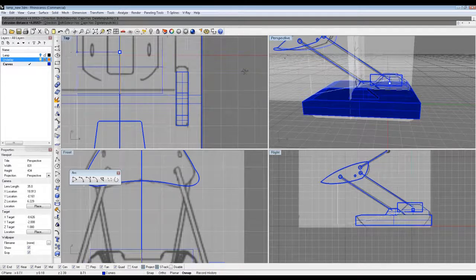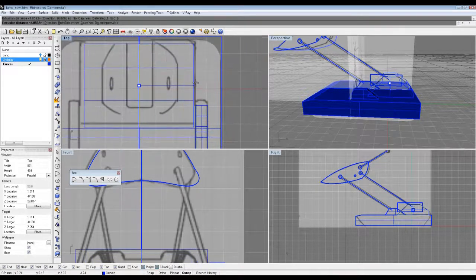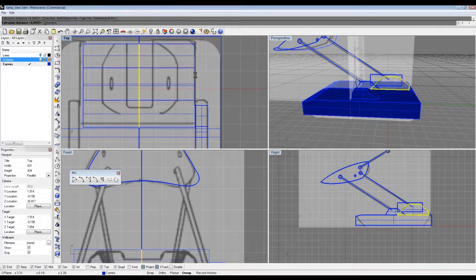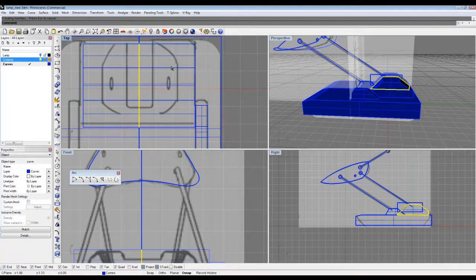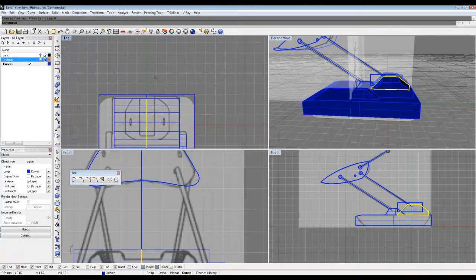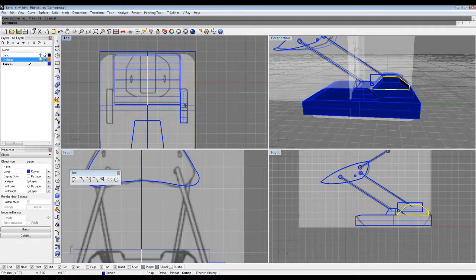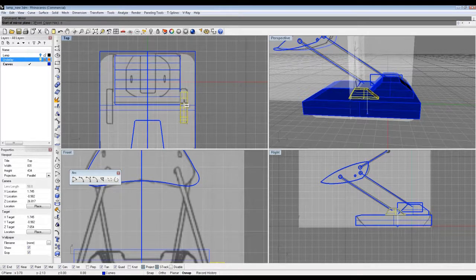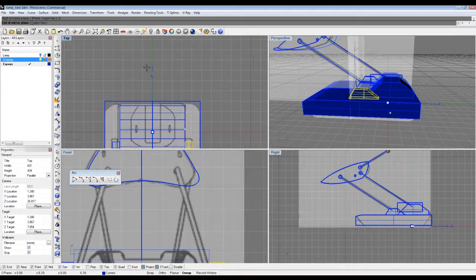And you'll notice that I keep going back and forth between extruding with both sides turned on and both sides turned off. It's just a matter of the fact that I built this thing on the 0 axis, so it's perfectly on the y-axis. If I have something on one side, I'm only going to have to model this once, so I can now mirror this along 0 and get it perfectly into place, and I know it'll line up perfect.